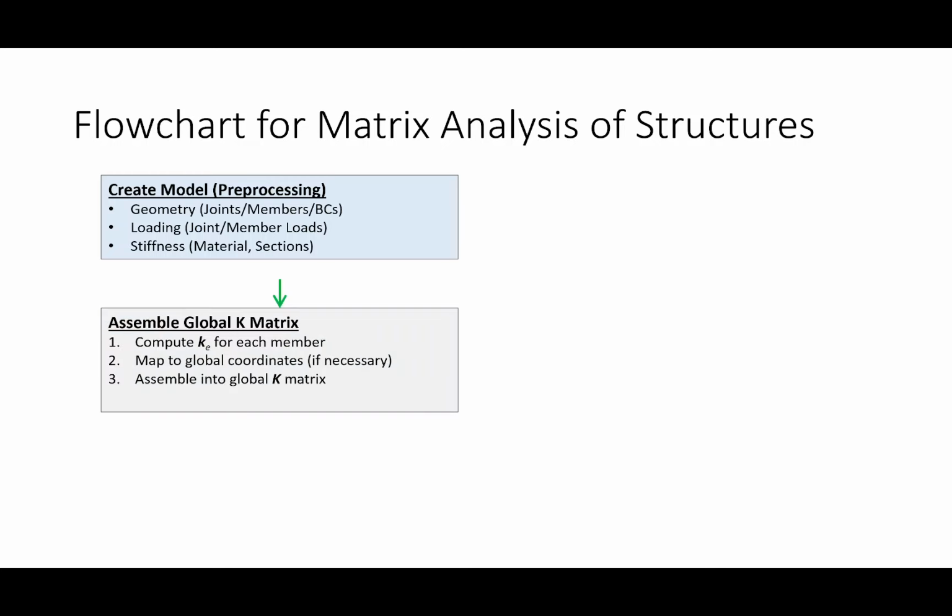So the first thing that it does, and I've got this here, we're going to do this in steps. The first step is it assembles the K matrix. And the K matrix is basically like the spring matrix, if you will, for the whole system, okay?